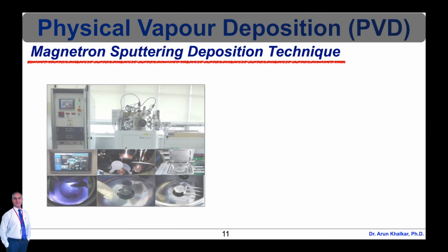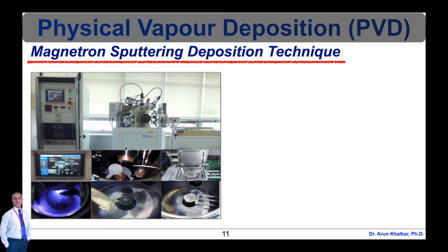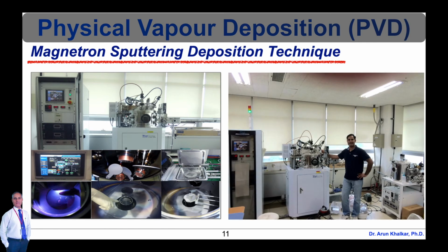Here is a typical magnetron sputtering system on which I have done my PhD work of thin film solar cell deposition. Successful magnetron sputtering deposition requires the correct choice of power delivery system. Magnetron sputtering can be done in either DC or RF modes, but the former is more common. Metallic films like aluminum alloys, titanium, titanium tungsten, titanium nitride, tantalum, nickel, cobalt, gold, etc.